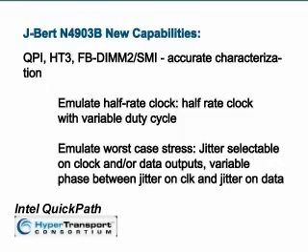And here is an overview of J-BERT's major new capabilities. For the new forwarded clock devices, J-BERT offers the most accurate characterization because it helps you to emulate half-rate clocks and to add stress conditions to the clock and data signals of these forwarded clock devices.